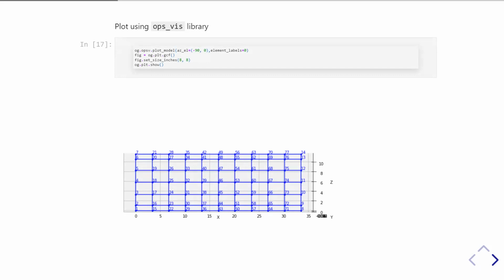In only more or less 17 steps, you are able to create your Grillage model, and that's the power of OpenSees Grillage. It wraps all the commands that you would otherwise use, which for this model itself would take more than 100 lines to generate in OpenSees. With OSP Grillage, in fewer than 20 lines, you can create the model in the model space here.